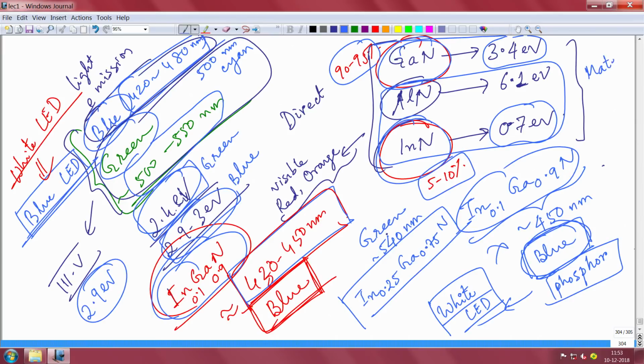See, these materials, when I say you are mixing and matching to form alloys, there is a lot of material science that goes behind it in terms of lattice mismatch and the difficulty in growing the material in the system. Typically, mixing indium nitride and aluminum nitride together has not been so widely studied, because it is a little difficult to grow aluminum nitride. It is also a little difficult to grow indium nitride.